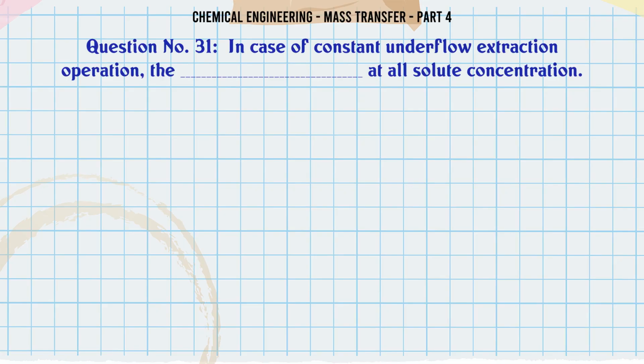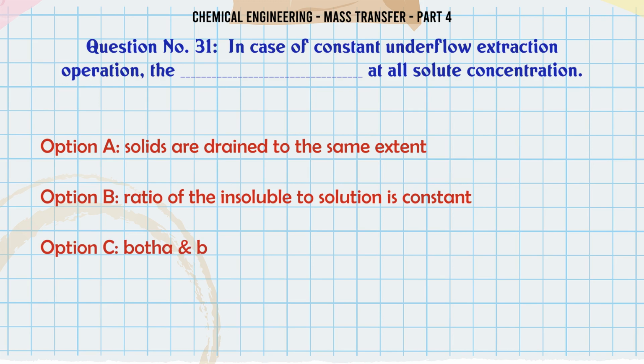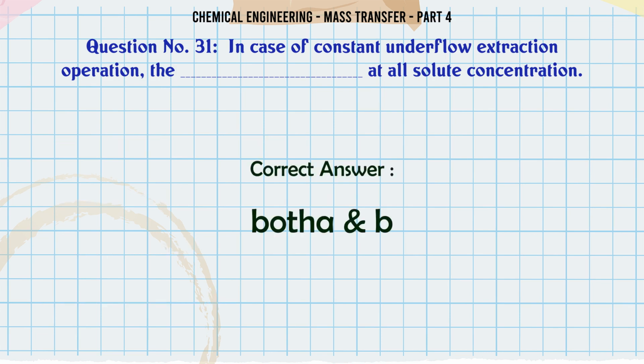In case of constant underflow extraction operation, at all solute concentration, A. solids are drained to the same extent, B. ratio of the insoluble to solution is constant, C. both A, B, D. neither A nor B. The correct answer is both A, B.